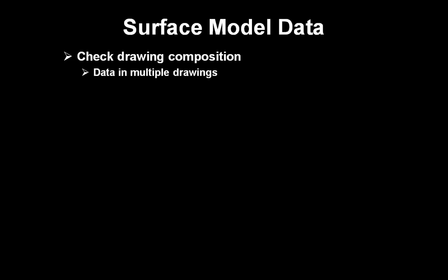For instance, there may be a base drawing that has the new building, the new parking, the geometry, the existing information, and then they will externally reference that into another drawing for the grading plan, where the notes and the actual proposed contours and things like that are. So there are probably as many different ways to organize a set of drawings as there are people out there. So you really want to look for that.